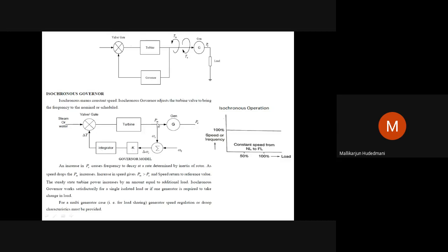Then the integral controller is taken in the path of feedback, that is making a correction to the steam or water or input fuel. So an integral controller will always look to see that the average error over a particular observation time span is null and made zero.